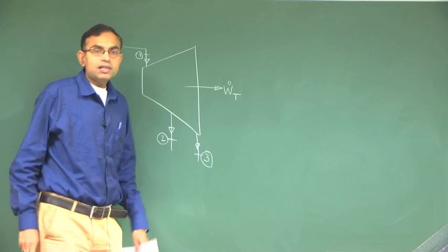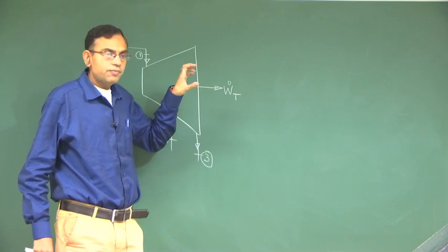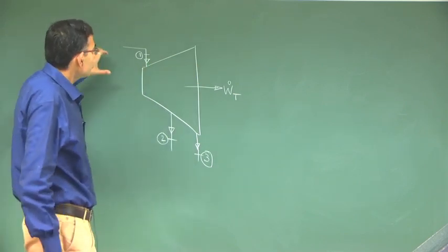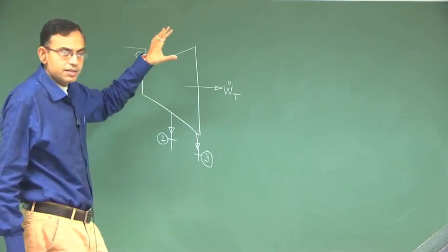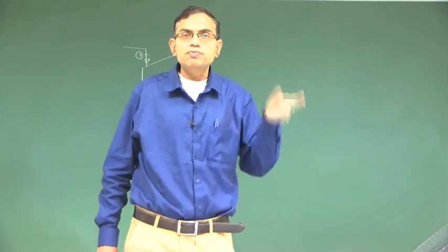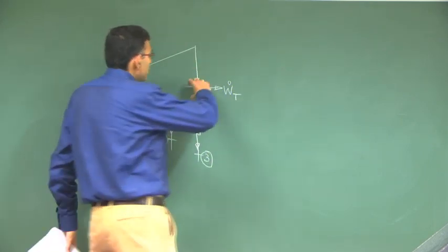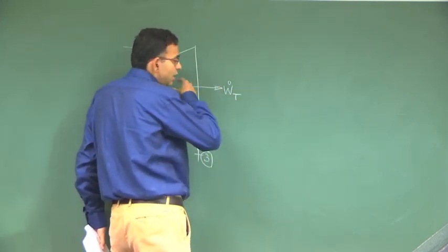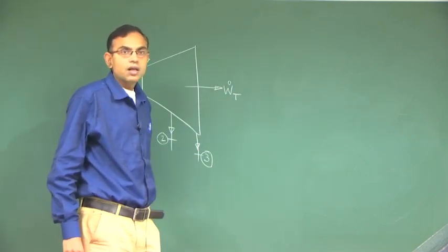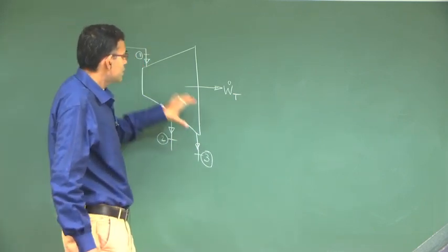To explain what a steam turbine is, you have steam entering from a nozzle with a high kinetic energy into the turbine, and it hits the turbine blades. There is a rate of change of momentum or angular momentum that gives a net torque with respect to the axis of the turbine shaft, and the turbine shaft starts rotating. That is how power is generated from steam.